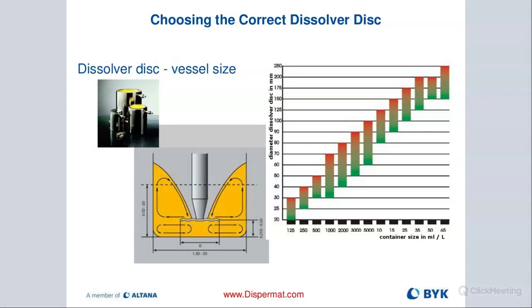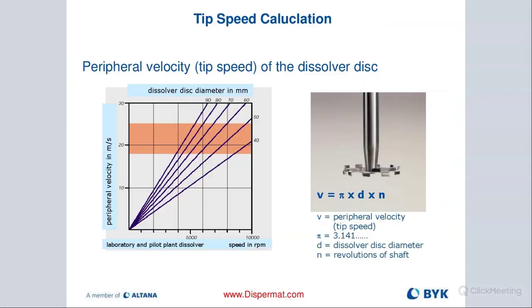And then if we're dealing with very thick materials, almost like pasty products, then we want to increase the diameter of our blade to achieve a proper pre-dispersion. So that's important. We also have that particular table on our website, so you can review that later when you are running your product to make sure you're picking the right blade size respective to your container.